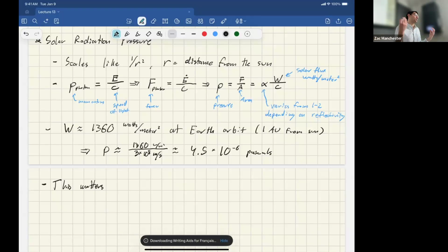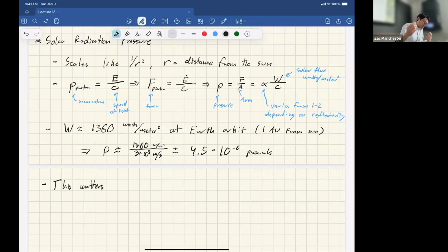Fun fact, to make a solar sail work and not just be a drag sail, you've got to be above this 600 kilometer-ish number. And annoyingly, many of the solar sailing demos that have been flown on small sats have been below 600 kilometers. So really just drag sails. Not to knock those people. The deployment and attitude control of those things is very hard. So they're getting at some important stuff, but they didn't really necessarily do solar sailing. So you've got to be above about 600 kilometers for this to really matter much.